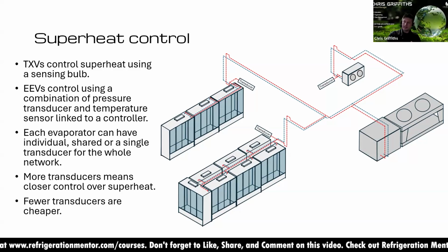So if we took that island of 7 cabinets, for example, 2 of them were iced up, 5 of them were operating okay. First point I would look at is it's probably not transducer related. It'd be more of a controller issue, say a superheat issue of miscalculating the valve opening positions based on those transducers.